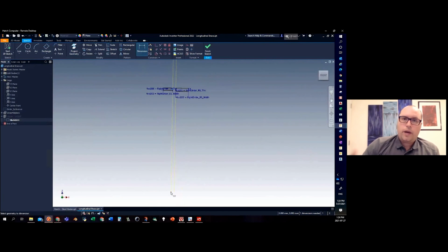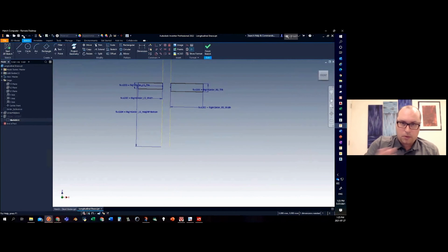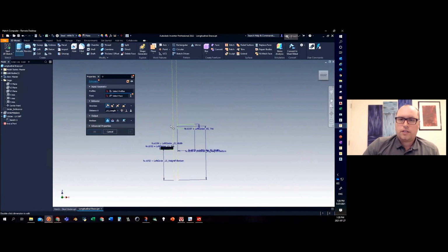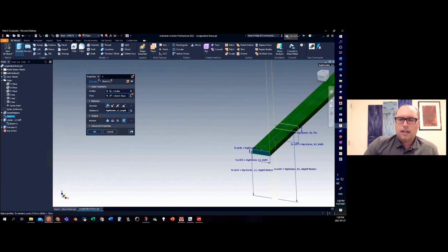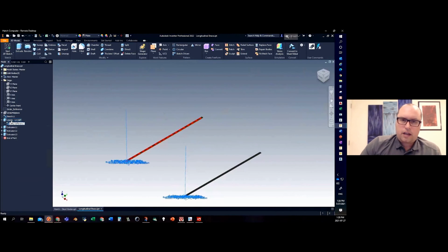So we ended up building that tool into Inventor itself, and then we can adjust it all. So here I'm just still putting in the geometry. For everyone who also isn't familiar with parametric modeling in Inventor, it's not like AutoCAD where I draw a rectangle with specific dimensions. I will draw the shape, and then I'll define the rules that create that shape.